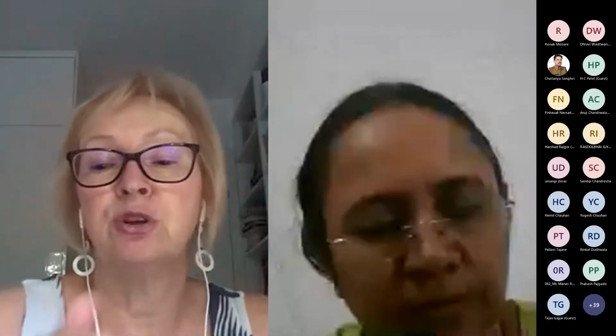Like in concrete, you have shear failure, flexural failure. In masonry, this is how shear failure looks, and simply the crack will propagate. But toothing is important to make them work together, because these confining elements are really critical, not so much to improve the strength, it is more to improve the integrity of the walls. And if you don't have the toothing done right, either physically by toothing or by reinforcement, then we have a problem, and this will be different behavior.